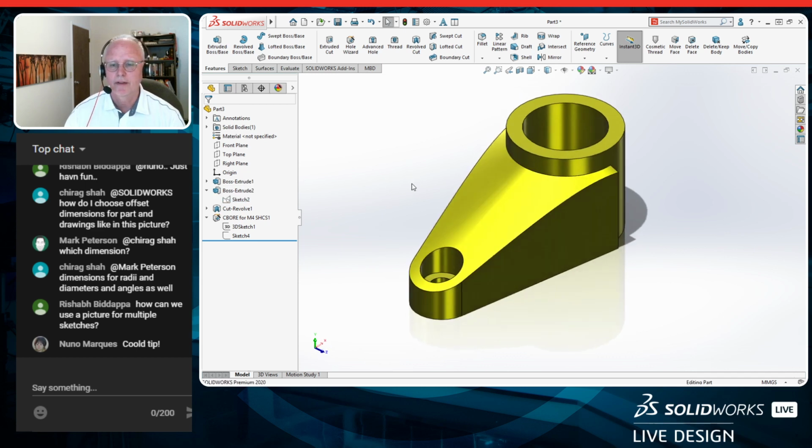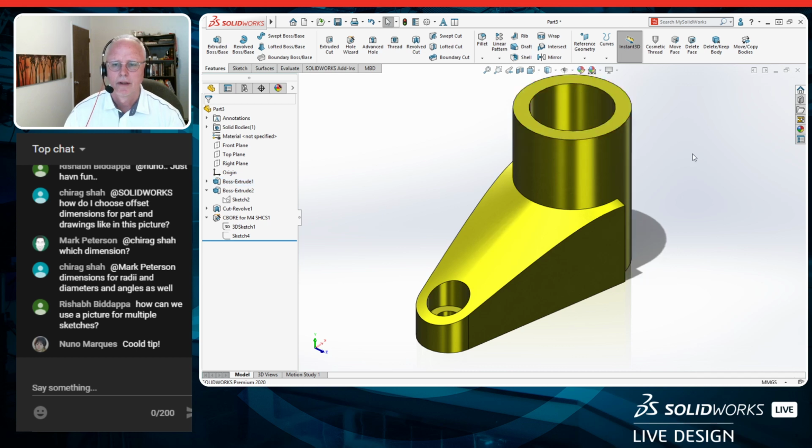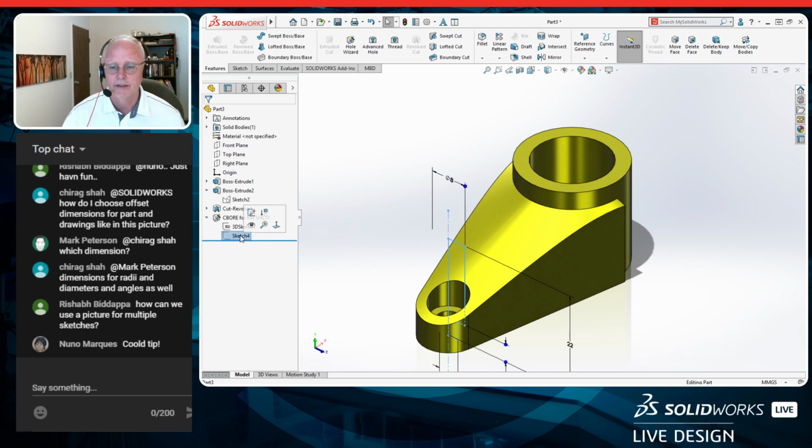The nice thing about doing it this way is if your model changes, let's say this thing gets taller, you're still going to maintain that dimension. I could have done some math and said, okay, the height of this was 22, and I went 4 from the bottom, so that's 18. I could have redefined the depth of the counterbore to be 18, but then my design intent wouldn't be captured. So I like doing it this way. Remember, these sketches are editable.